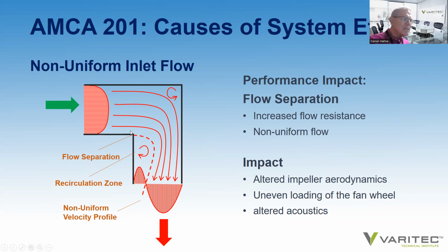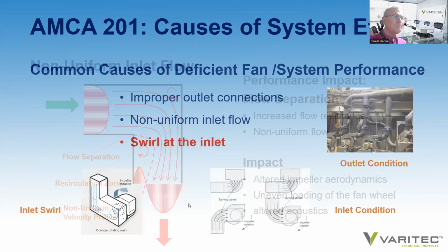And the inside of the transition sees a negative pressure zone forming. Consequently, before you can really measure the amount of airflow in that duct system, you have to give it room, you have to give it space to achieve a uniform duct velocity.